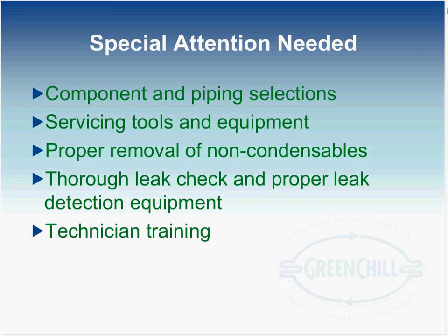You can accomplish this by using a high quality grade of CO2 to charge the system. Filtering the refrigerant as it's being charged can be done. Of course, a proper evacuation of the system prior to charging the system with CO2. Obviously, we'd recommend a triple evacuation, achieving a micron level of 300 microns or less.